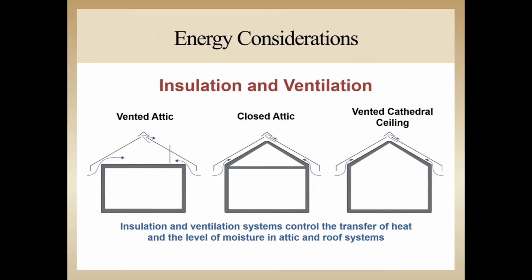Energy conservation and moisture management must be considered in roof and ceiling design. Increasing the amounts of insulation and the levels of airtightness are required. It leads to the development of new concepts and systems. While increasing energy efficiency is the ultimate objective, managing moisture as it migrates through the roof and ceiling systems must always be addressed, making ventilation design critical to the long-term performance and the durability of the components.